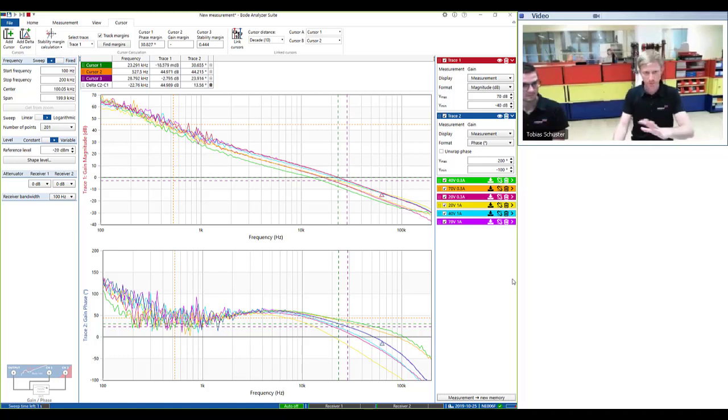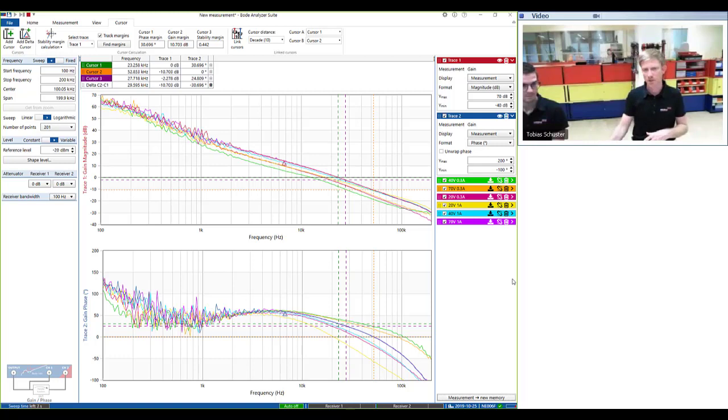Of course, they are not beautiful because that's a trade-off between speed and noise. You can now reduce the receiver bandwidth to clean up the curves. You can use a 10 Hz measurement, but the 10 Hz measurement will not take 5 seconds. Let's wait a little bit, so it takes 50 seconds. That's why we didn't do it right now, but then you will get a less noisy curve.